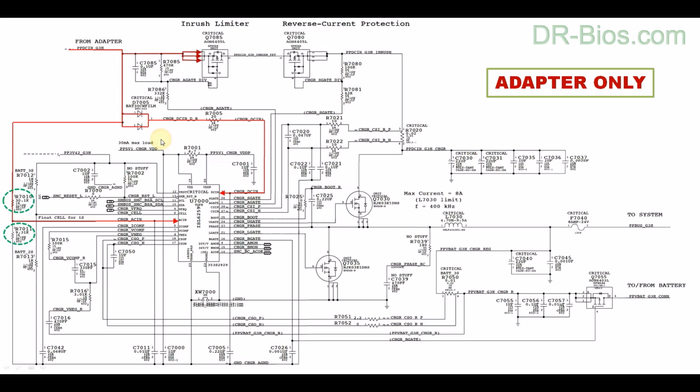As you see, the input voltage enters the back side of the first MOSFET, and the gate pin of this P-channel MOSFET gets pulled up through a resistor. And that causes the source and drain pins of the MOSFET to be completely disconnected from each other.